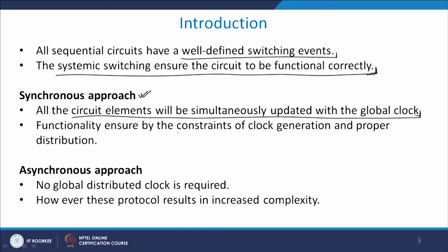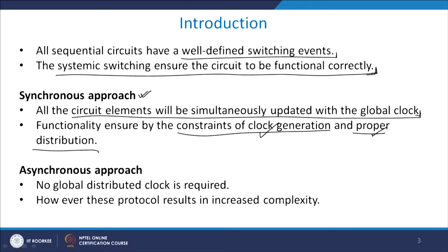In a synchronous design, synchronous basically meaning that your data is synchronous with the clock, the functionality is to ensure the constraints of the clock generation and proper distribution, that means the constraint of setup time and hold time, as well as how you are distributing the clock in a spatial domain. These are the 2 very important parts to ensure that the chip is working properly, and these 2 things ensure the functionality of the chip.